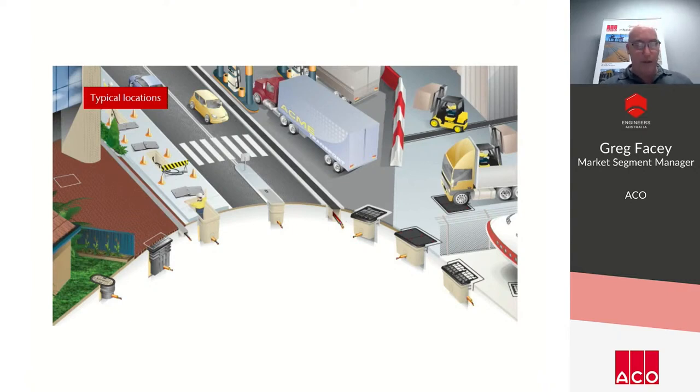However, in solid pavements, where there's vehicular and pedestrian traffic, a rigid pit is recommended. Rigid pits are not just used in trafficable and vehicular applications, but certainly can be used in lighter duty applications as well. So they're fairly broad in their application. So FRC, precast fibre reinforced products, Portland cement concrete pits cast in situ, so typically boxed up pits which are poured on site, and polymer concrete pits, which is a precast resin composite material. And the advantages are they're strong, rigid, and versatile.